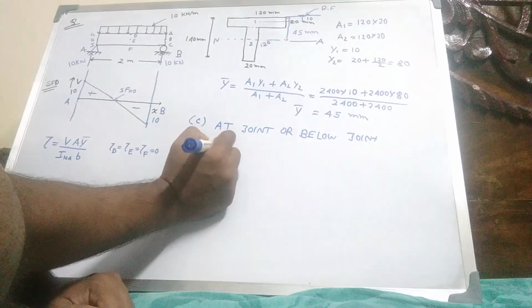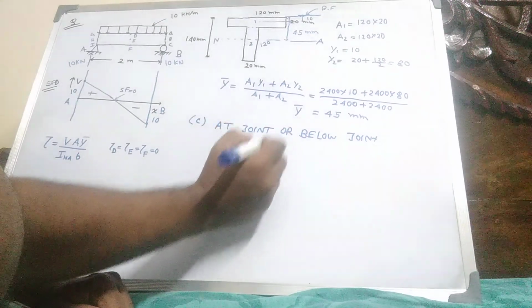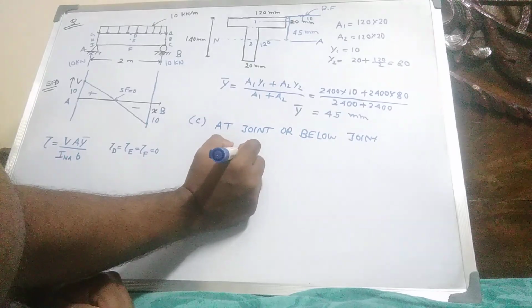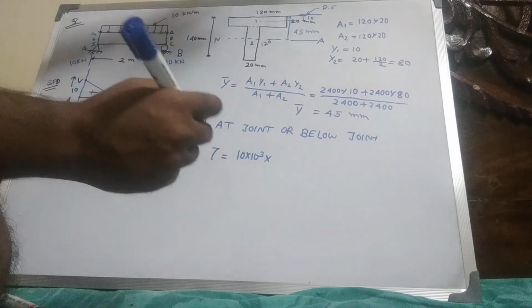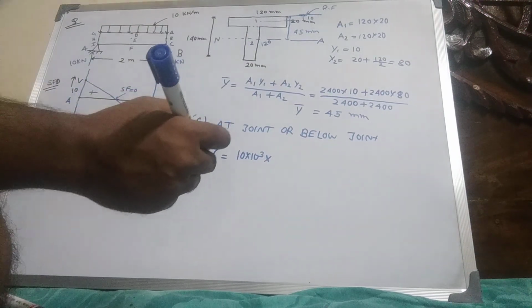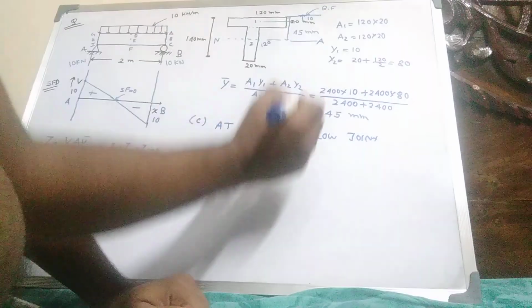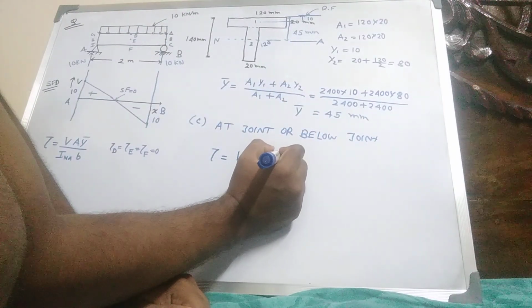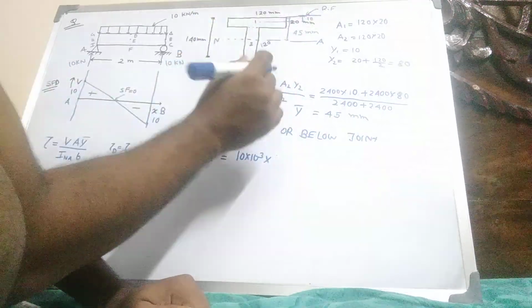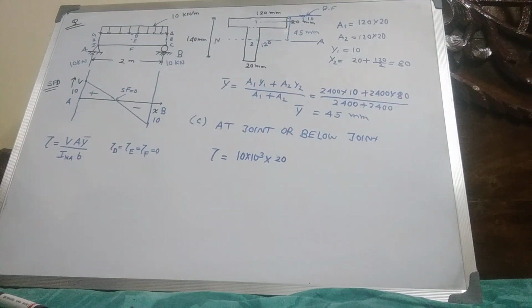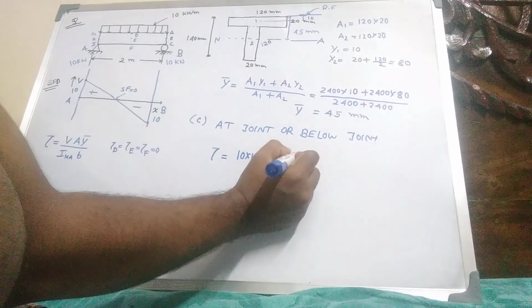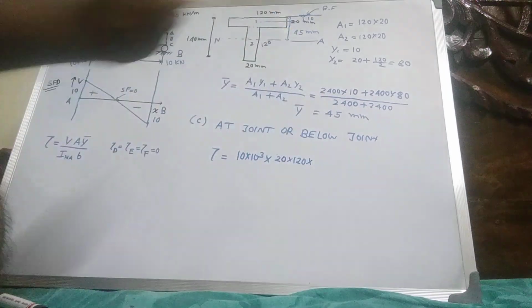Shear stress equals shear force 10 to the power 3 into the area below this point, which is 20 into 120, into y bar.